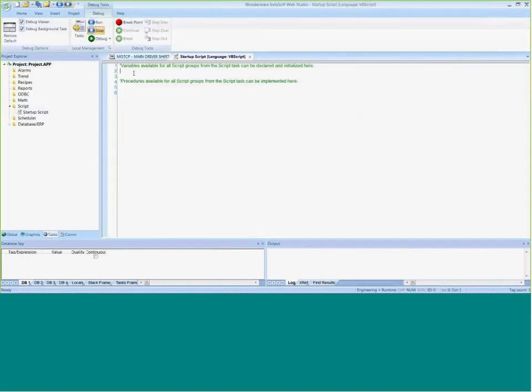startup script. We just set it up at the top here. Since PLC1 is an InduSoft tag, when you use that in a VB script, you have to precede it with a $ sign. I'm just going to type in PLC and notice that it has that IntelliSense, and it's already starting to form that tag for me. Then I can say equal, and remember you have to put double quotes around it because you're referring to it as a string.